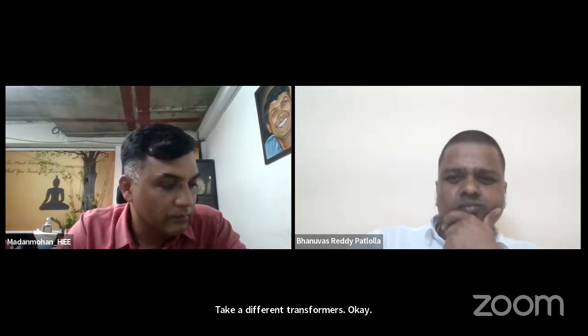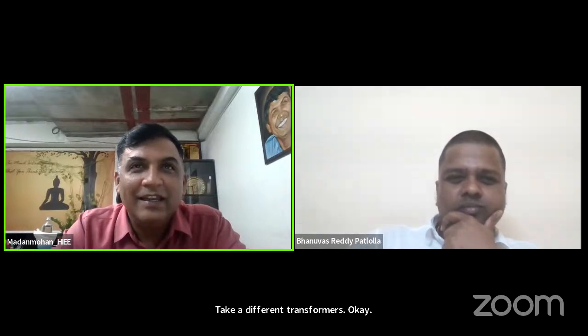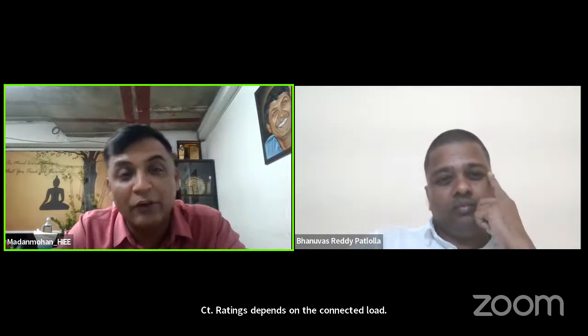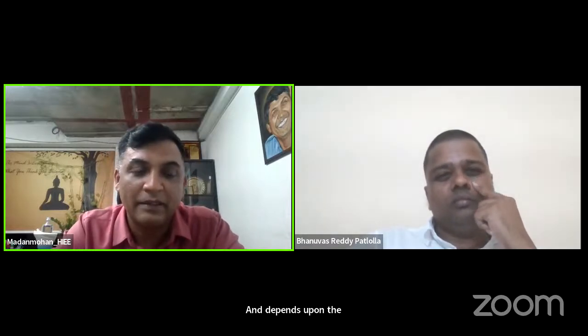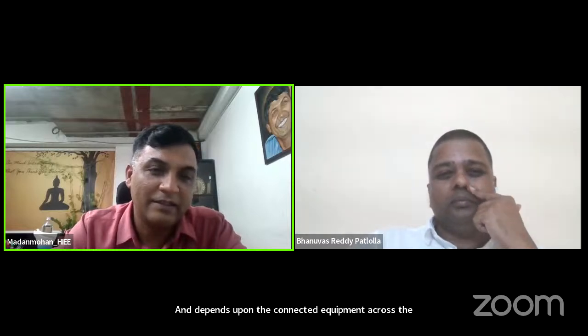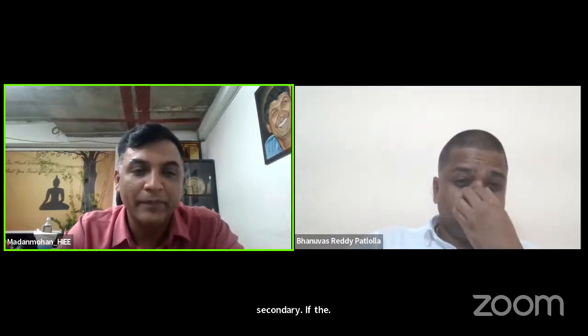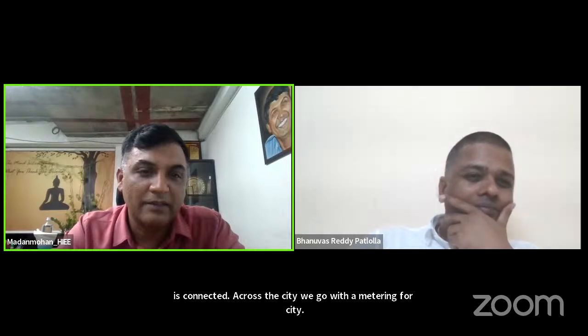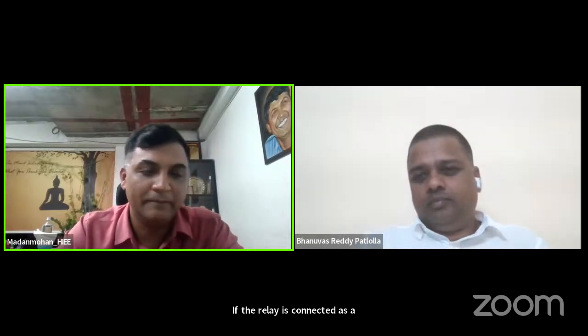Okay. There's a question from Neeraj on YouTube asking how we decide the ratings of a CT. CT ratings depend upon the connected load and the connected equipment across the secondary. If the meter is connected across the CT secondary, we go with the metering core CT. If the relay is connected across the CT secondary, we go with the protection core CT.